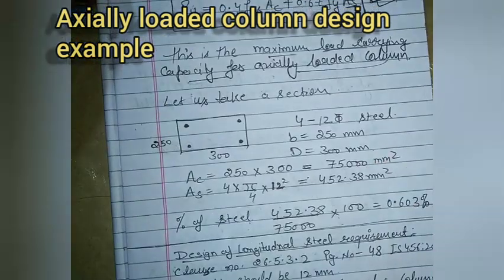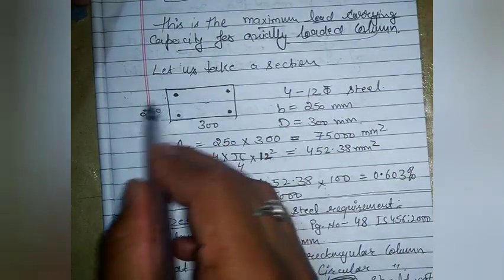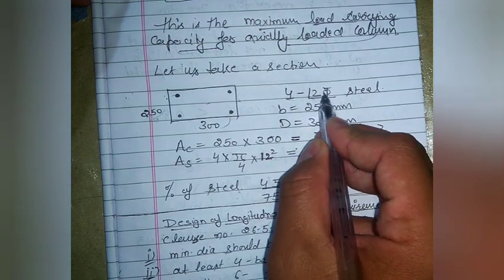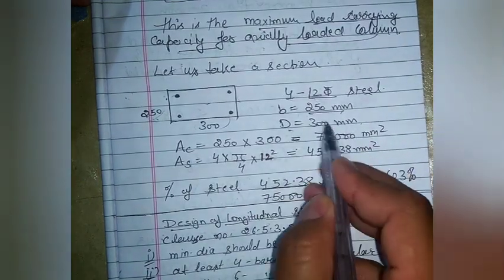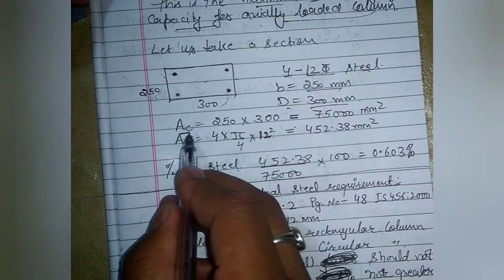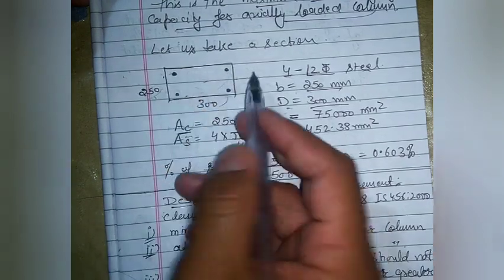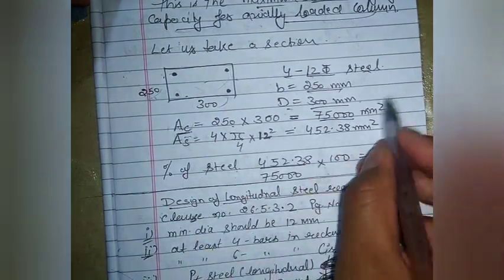So let us take a section here. We have a 250 by 300 section. Let us take 4 bars of 12 mm dia, with Torsteel being used here. So width is 250, depth is 300 mm. We can calculate the value of Ac, the area of concrete, since compression is due to concrete. So area of concrete is 250 into 300, that is 75,000 mm square.